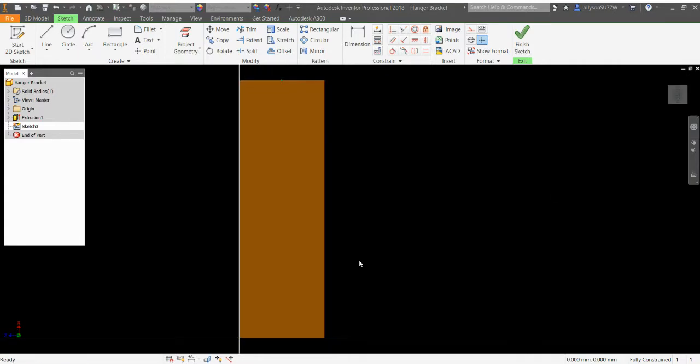So when I first looked at that keyhole, I just saw two images. I saw a square and a rectangle. And for me, it was easier to do a rectangle and a circle. And they actually give you dimensions that you can use. So the first dimension for the cutout is the rectangle. And so I need it to be 18, I'm not inches, millimeters. 18 millimeters wide by 65 millimeters tall.